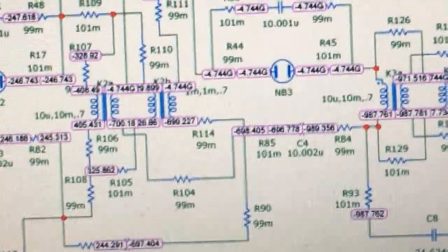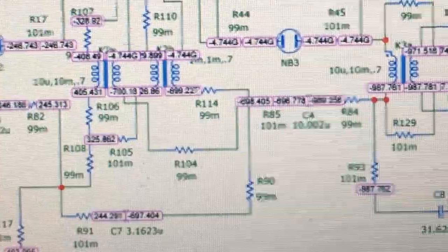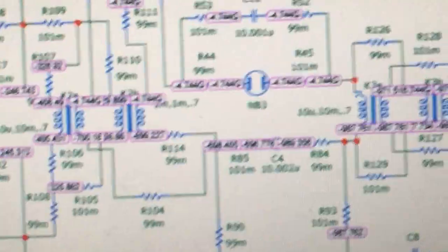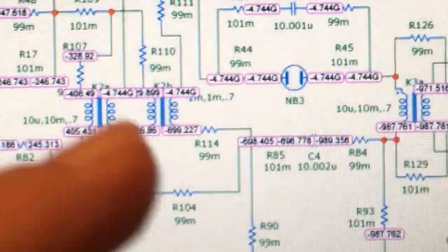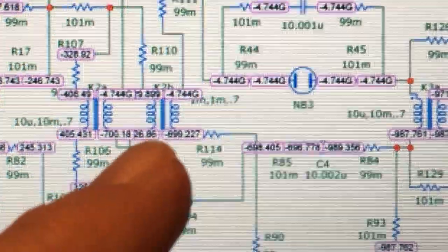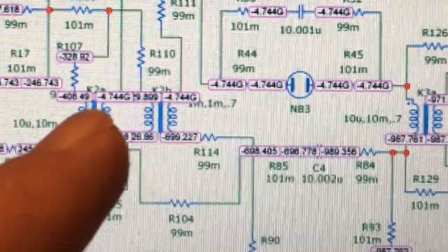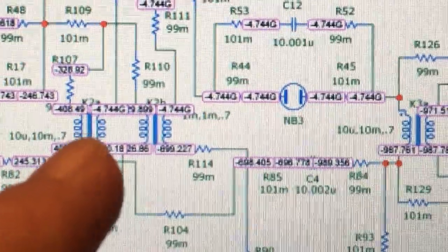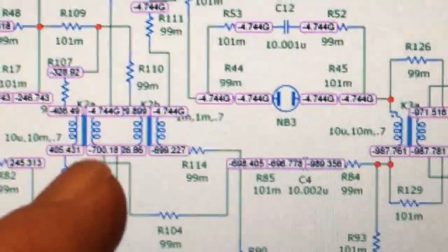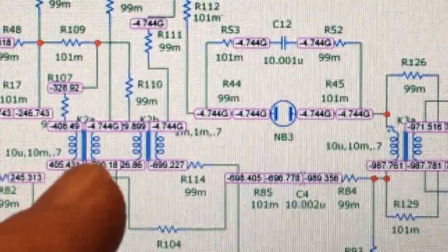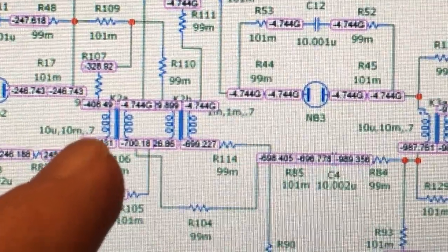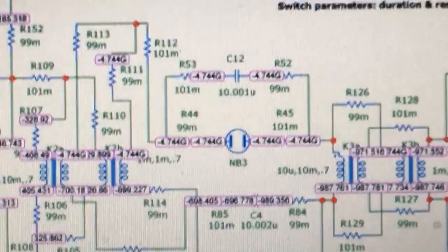Because the easiest way to turn off this circuit, and the only way that I know of, because it's going to always be on, is you take away, where's my finger? You take away the coupling. In other words, let's say this is an iron bar, an iron center to this transformer. You take it out, and you separate the coils. So you have to wrap these coils on separate coils possibly, and slide out one from the other to bring the coupling coefficient down to 0. And then this thing stops itself.